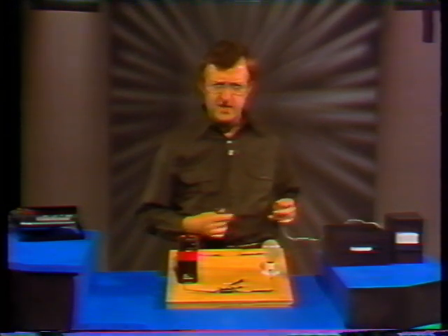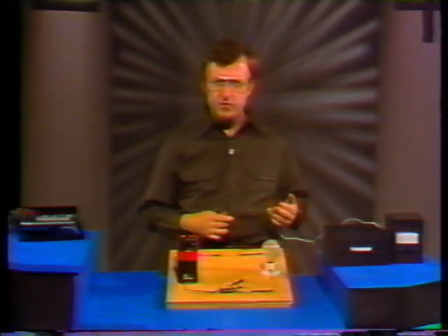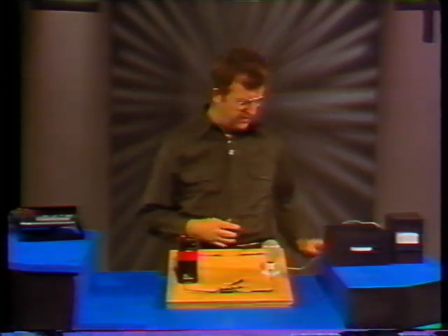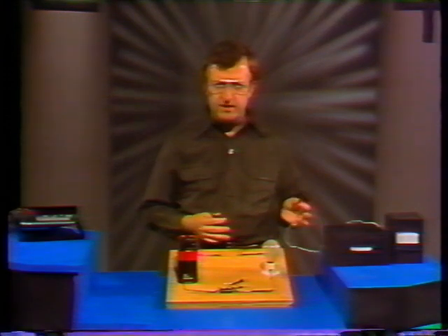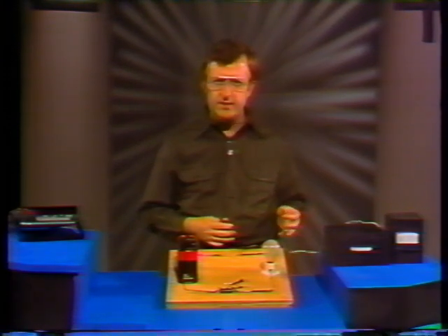We're going to use the voltmeter next. It's set up differently. It's hooked up in parallel across the circuit. And it makes sense when you figure that voltmeters measure the difference in potential between 2 points. So a voltmeter has to be hooked up between 2 points that you want to measure. Now, voltage doesn't flow through a circuit, so it would be pointless to set it up in series like an ammeter.